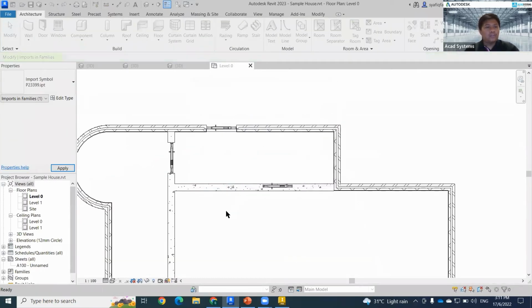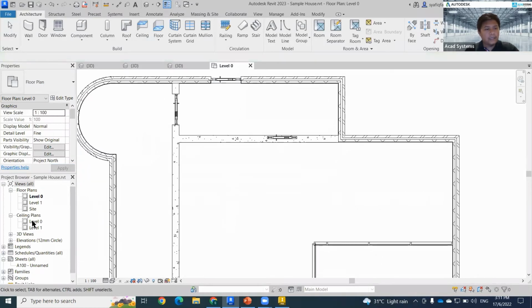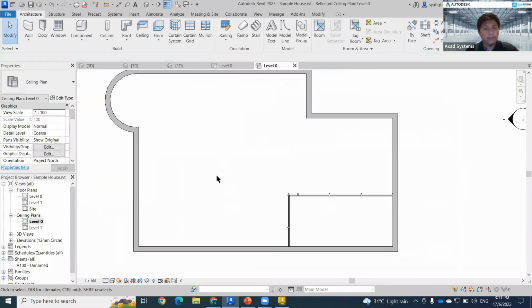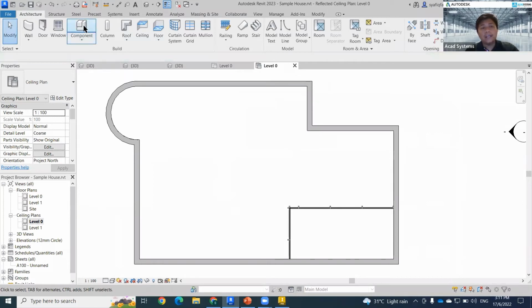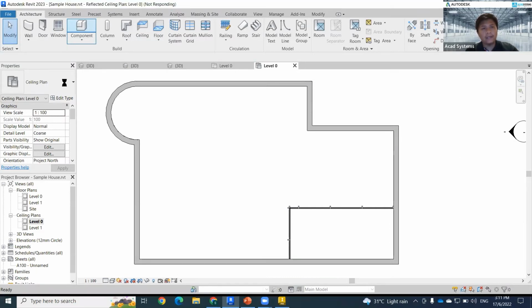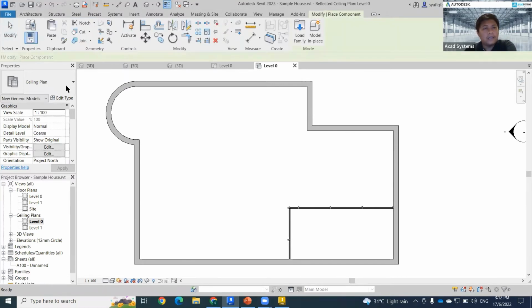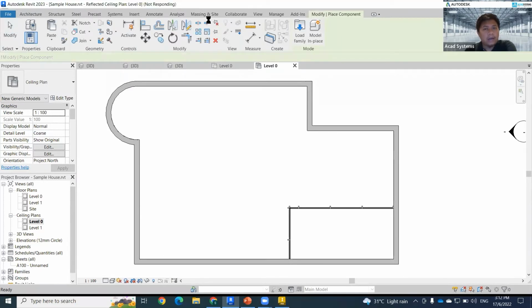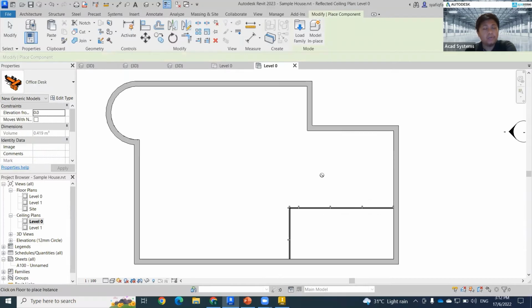In this case, if I want to insert a light, I already have the ceiling in my model. Go to component, go to the next one, and look for light. I have one file which is a big file, not a converted file, the table. I just need to click on this component and choose whatever type I require. So that will be the step to insert a component.